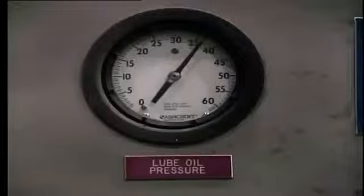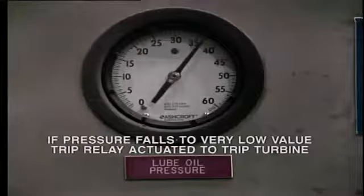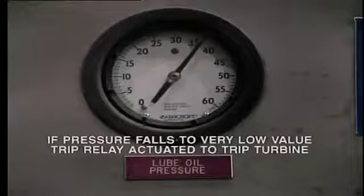Lube oil is monitored continuously, and if pressure falls to 0 or a very low value, a trip relay will be actuated to trip the turbine. Note that this relay will also prevent the opening of the turbine stop valve if lube oil circulation has not already been established during startup.